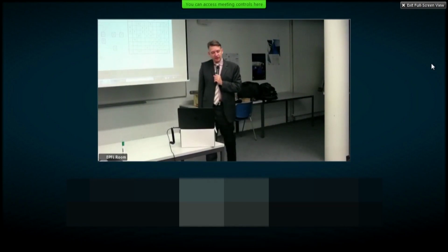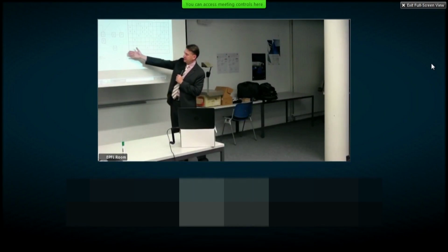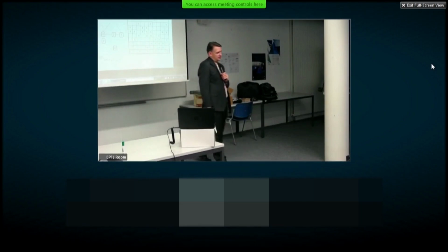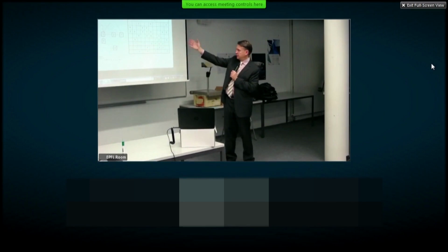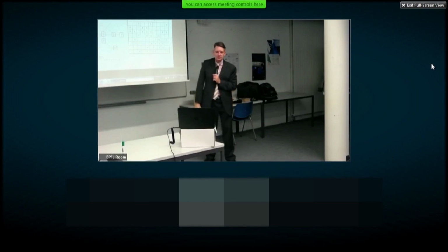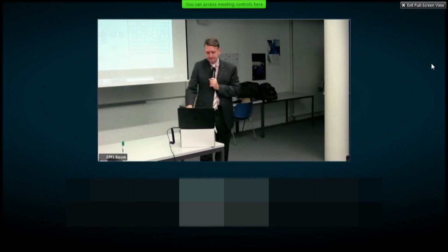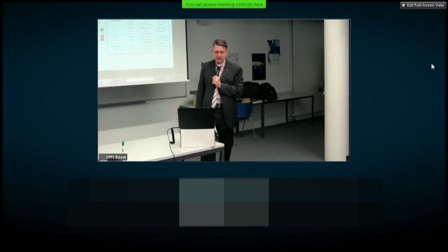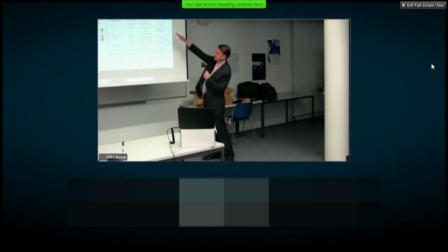So if you do have a liaison diagram, shown again, this is the same one on the left here, you can just translate that to a matrix. Right? The matrix, this DSM here, I'm using X's instead of ones, but these two contain exactly the same information. One is a graph view, and the other is a matrix view, but they're identical. The same information, just presented in a different way. And of course, if you pay close attention to the matrix, you'll see it's actually symmetric. So then we can say, well, what kinds of interfaces? And here come the 4 types that we just discussed: the physical connection, energy flow, mass flow, and information flow.